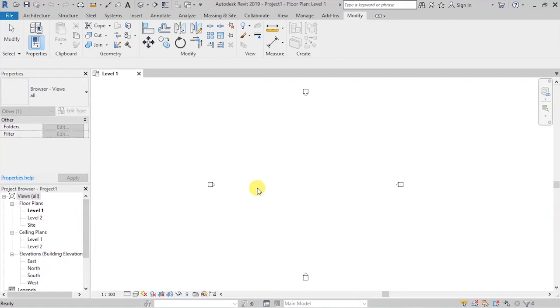We'll have a level for the ground floor, which is going to be at 0 elevation height. We'll have a level for the ceiling because we want to have our ceiling plans in place, and we will also have a level for the roof, which is going to be at an elevation of, let's say, sill to story height of 3000 millimeters. That's 3 meters, and from there we can now start creating the project.